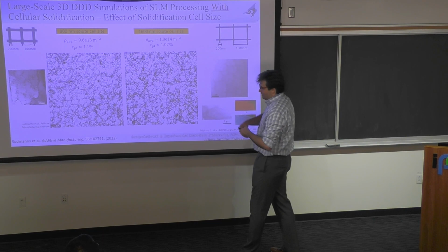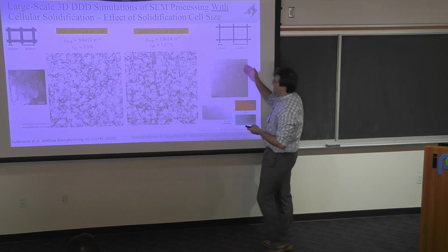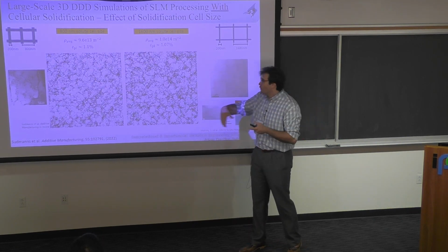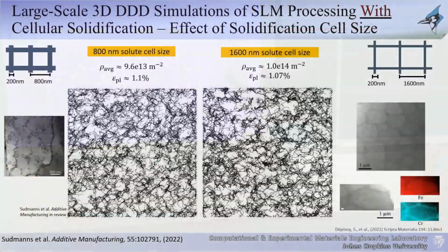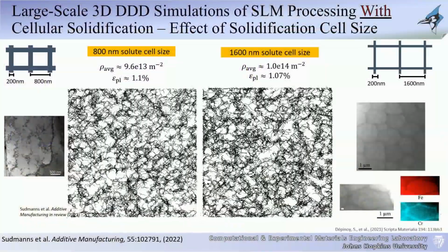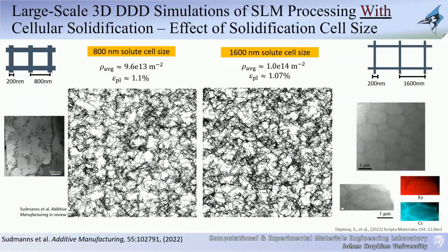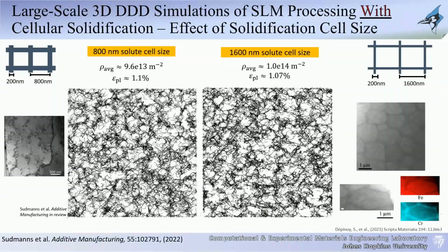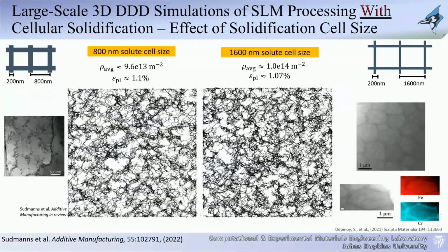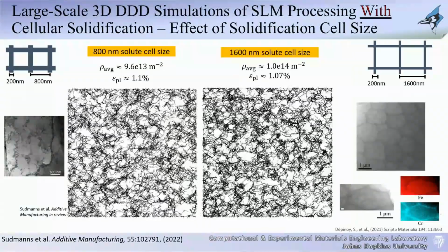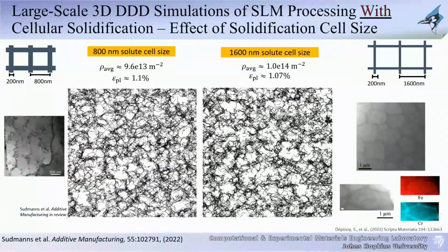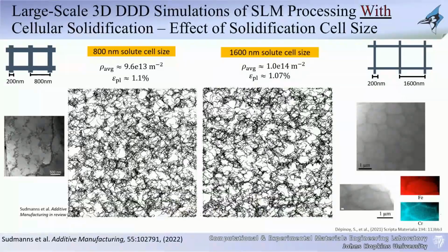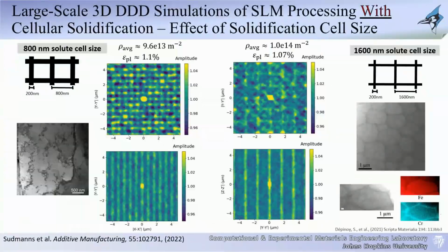There's a lot of analysis that we could do. One other example is if you change the laser power, the cell structures are different. You still get the 100 oriented cells, but on a larger scale. But interestingly, internally, you start getting alignments of dislocations along a 110 orientation, which is typical when you have general plasticity. We did these calculations again at 700, and for the smaller cells with the higher energy, you see the patterns forming.